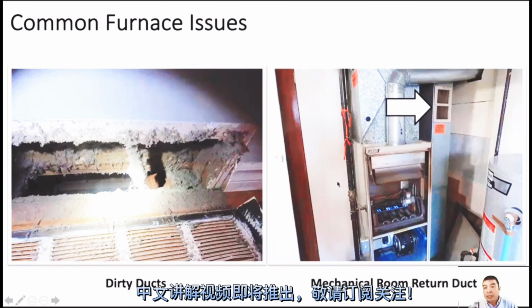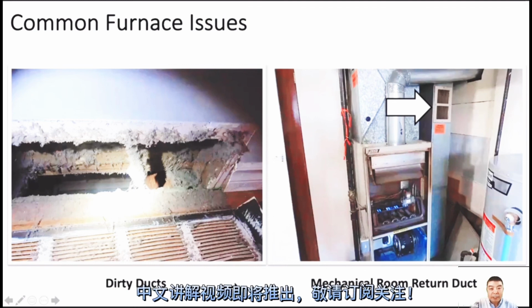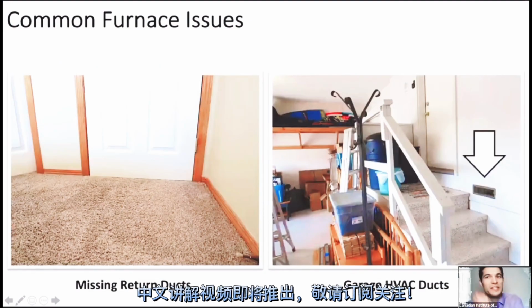Another issue is, if you don't have a very good balance of airflow, you're sucking all the air from the return air plenum in the mechanical room. If the mechanical room is opening, maybe it's good, right? Generally we just don't want to see that.